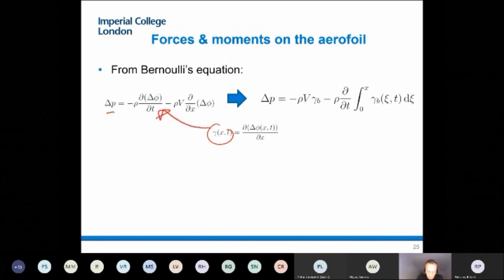So the first equation, or the second term on the equation, I don't know why I changed the order, gives you that the local pressure is equal to the local circulation. It's proportional to the local circulation scaled by the velocity. It's a classical solution again of potential flows, stationary potential flows in general. But then you have another term, which is because we have the dependency on the acceleration of the flow.